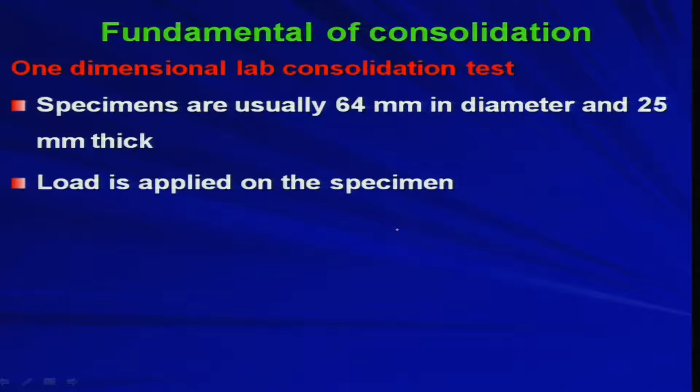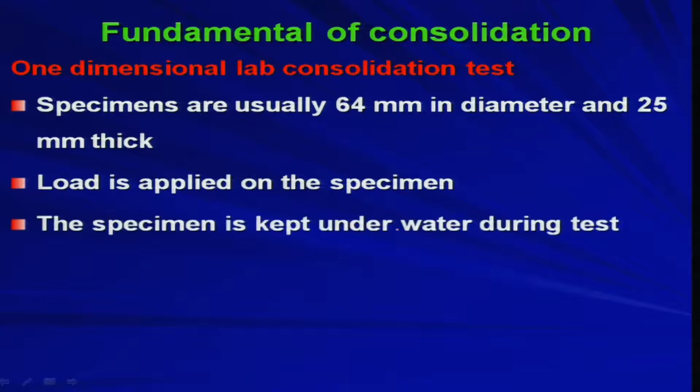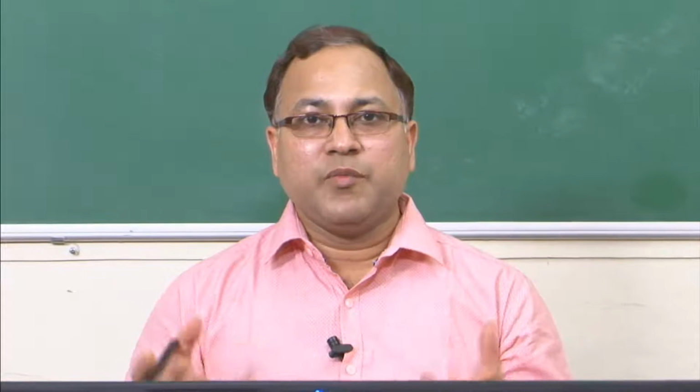Thick means the depth or the height. So, load is applied on the specimen, as I told you, externally applied load will be applied. The specimen is kept under water during the test, it will be completely submerged. That means you are considering completely saturated condition. So, whatever water will be coming out from the soil matrix, there will be no change in say air voids or something like that, right. So, whatever volume change you are getting, that is due to the expulsion of water.